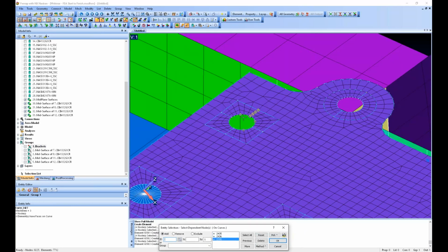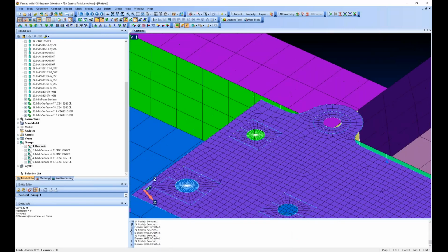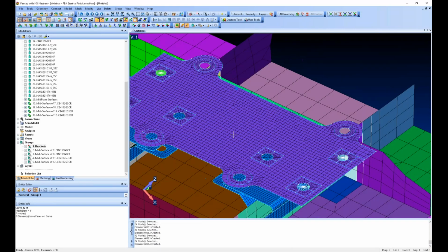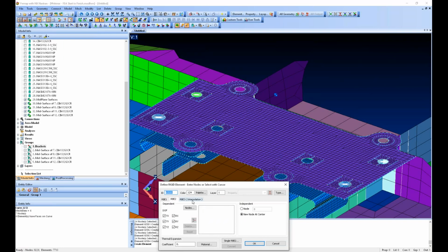And the last one here. Now I do have an option where, if I wanted to pull loads from these connections, I can put C-bushes in there. That's likely what you would want to do. In this case, just for time and simplicity, I'm just going to connect another rigid directly to it.